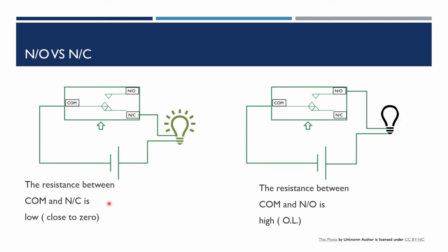In order to see that it is normally closed, you have to have a very low resistance, I mean like 0 ohm or 1 ohm, depending on the value. So maybe this is a low range, 0 to 10 ohm. If your resistance value is between these two numbers, it means that this terminal is normally closed.